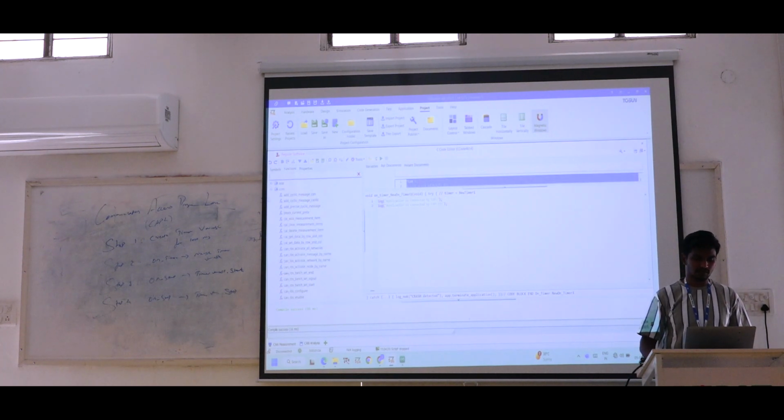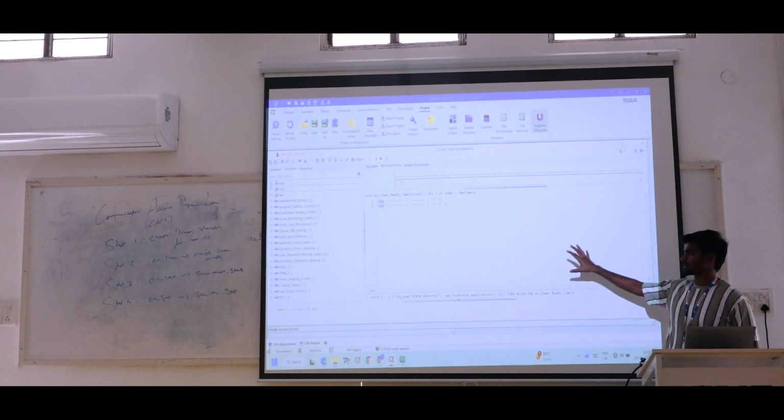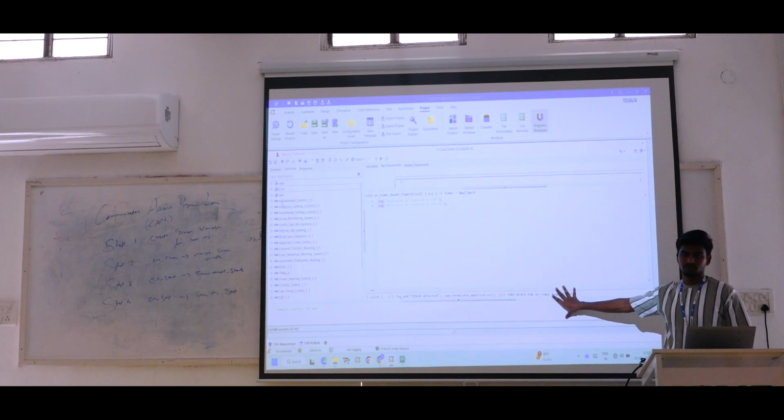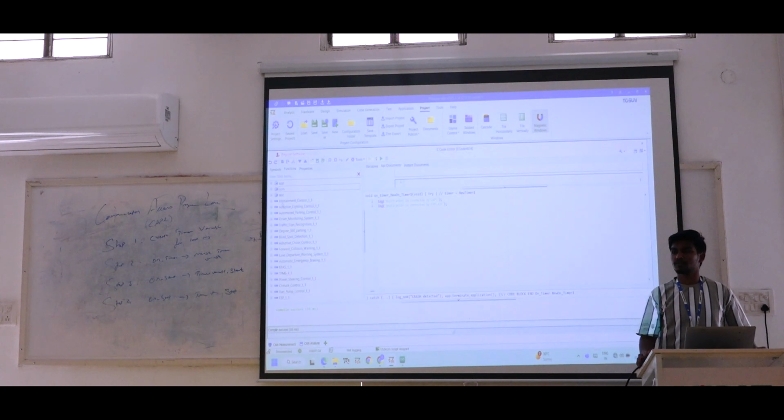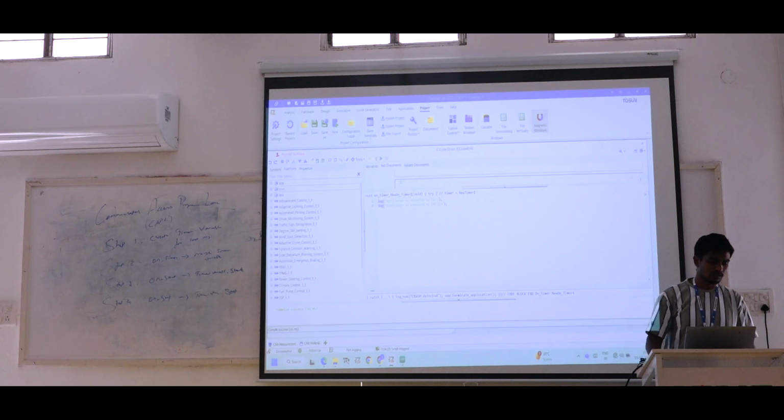In this functions column, we have 3 options. One is for test case purposes. Communication is for accessing bus-based communication. The application is for the system variables and accessing the automation of the entire tool. So using these application functions, we are able to map the hardware also. We are able to create the channel IDs, which means channel count, channel mappings, add the database, and whatever the database contains, everything you will see here.